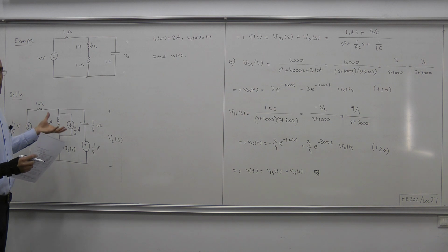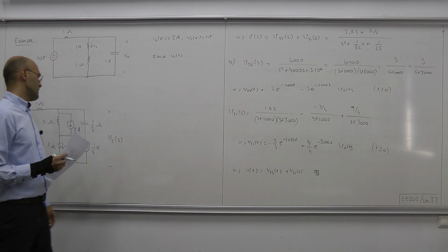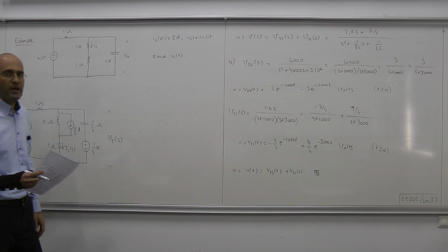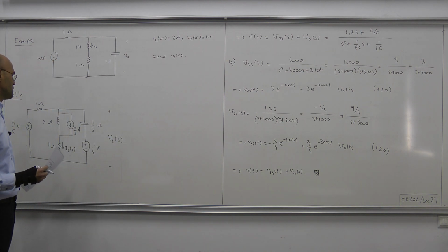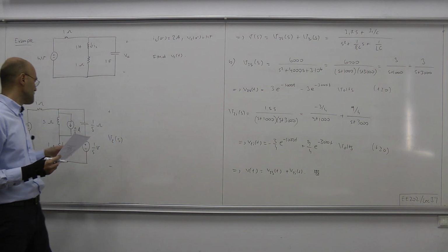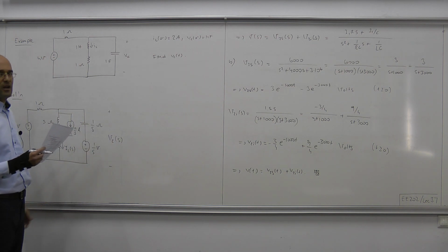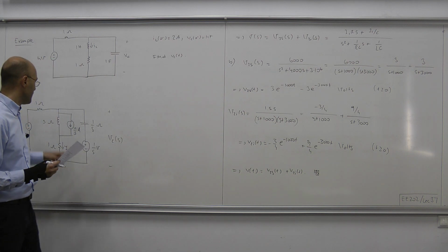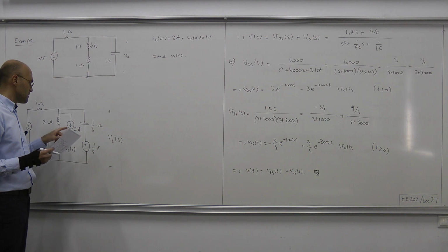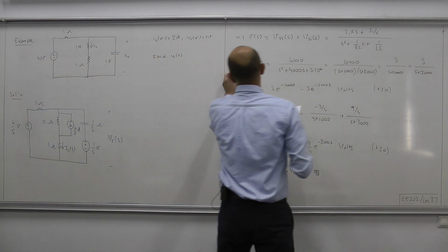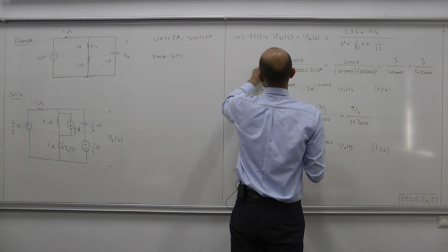Now, we're going to solve this circuit, treating it just like an LTI resistive circuit, and so we have many methods. We can use node analysis, mesh analysis. We already used node analysis in one of our previous examples. So for this case, let's apply mesh analysis. But for that, let's reduce the number of meshes by applying source transformation to this pair, the impedance and the current source. If we do that, we will have only two inner meshes.